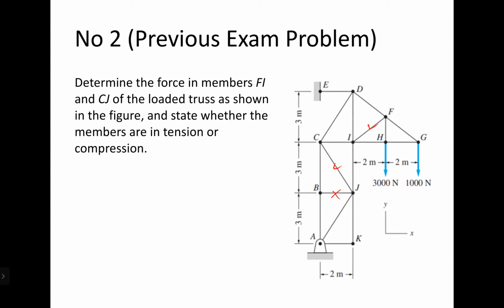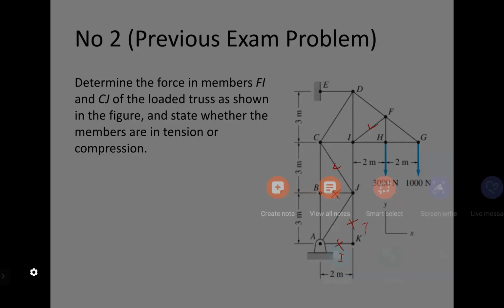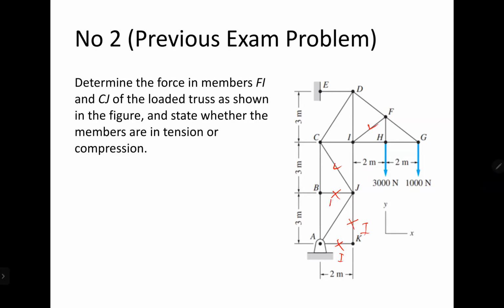AK and JK, that one is a zero force member as well. This is the first type of zero force member, and this one is also the first type of zero force member. So those three are zero force members. Then after that,